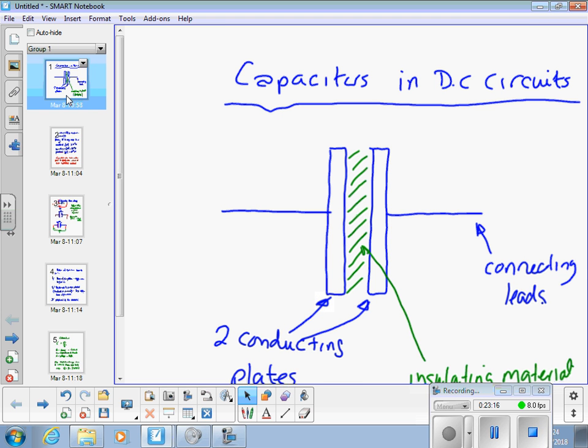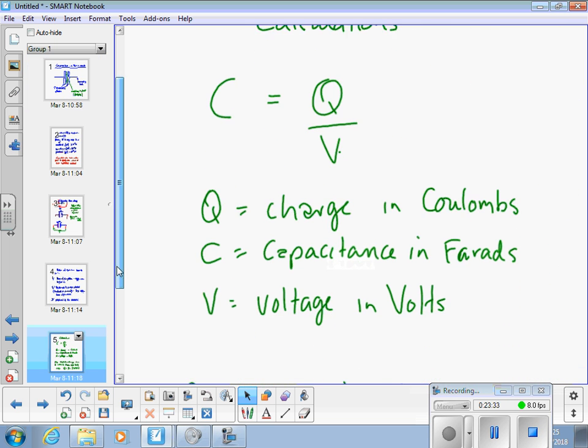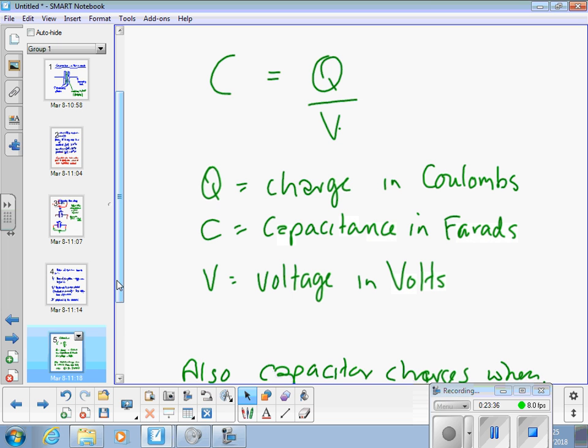That's because you're applying a fixed voltage and you're going to let the current gradually reduce. Next week we'll cover it in detail. They're quite useful. What you'll learn next week is that the charge cycle, the time it takes to get almost to 10 volts, is a consistent thing, and therefore capacitor resistor circuits are used in timing circuits because they're consistent and repeatable.